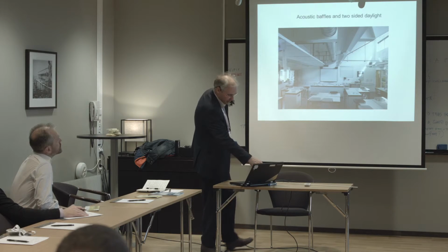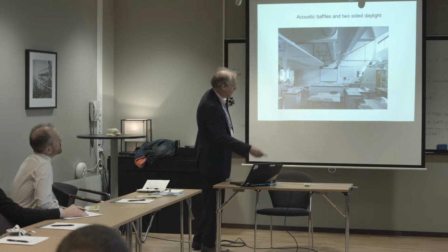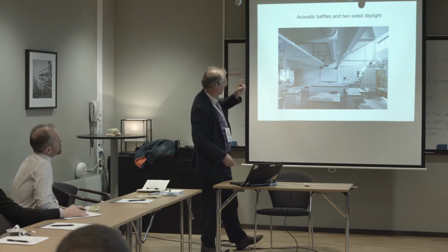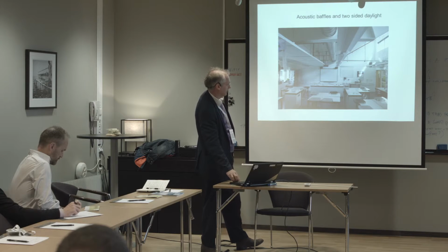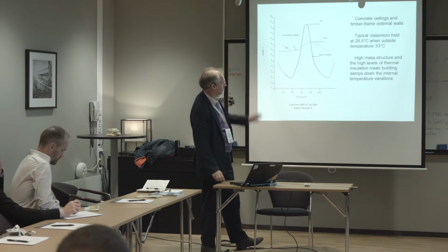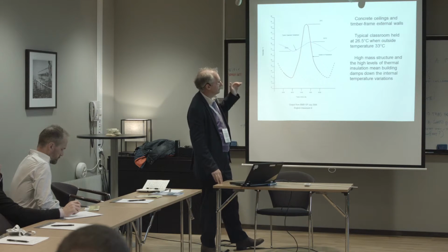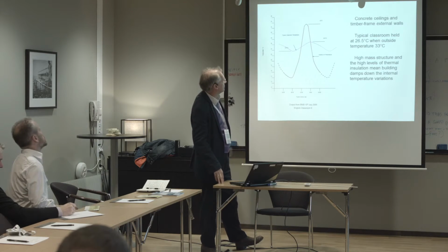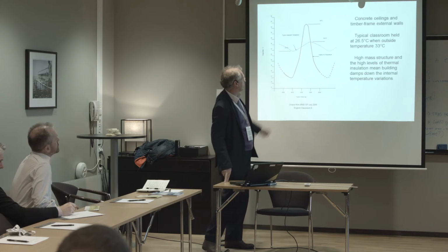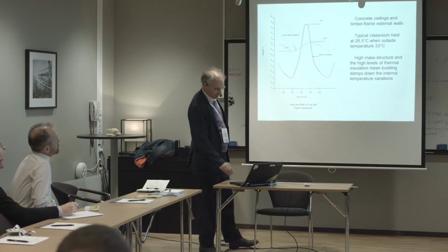It's got acoustic baffles, which it needs, you can see them on there. The slight problem with that is cleaning of those, I would suggest. Is that sort of dust traps, but this is a fairly 90s design now. But it did perform quite well. And the really impressive thing is the way it stabilizes the temperature. So there's the outside temperature going right up, but it's really constant, 26.5 when it's 33 outside. So that's the advantage of the thermal mass.